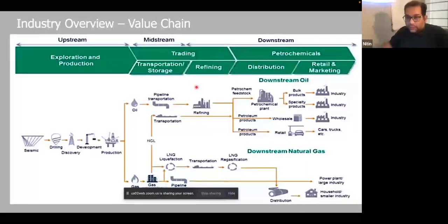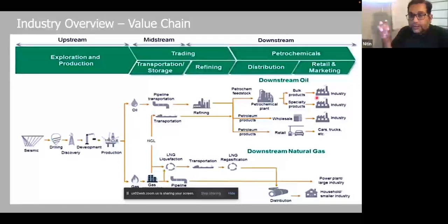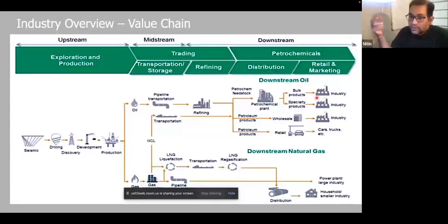segregation of molecules. Okay. So when I say petrochemical, say for example your ethane, right? Ethane is the primary gas which goes to the petrochemical complex, and ethane goes into the cracker, then it changes its molecular structure and becomes ethylene gas, the precursor of polyethylene. That ethylene goes to the polymerizer, and then becomes polyethylene pellets. The reason we are able to do that is because once you have bulk products, you can go for any kind of formation in multiple industries. So the polyethylene becomes the bottle or any kind of plastic thing which we see, and your